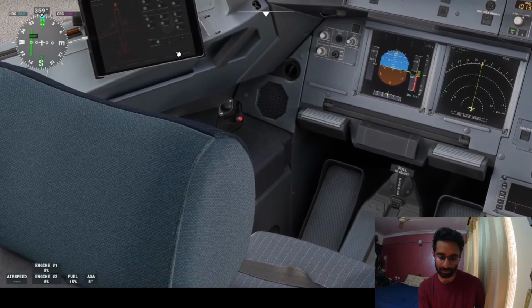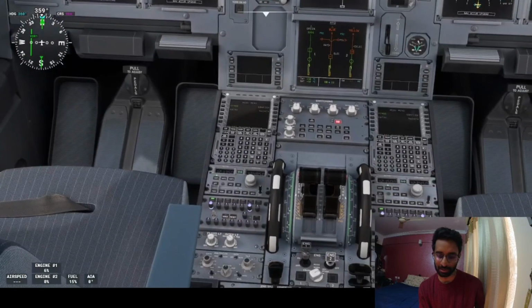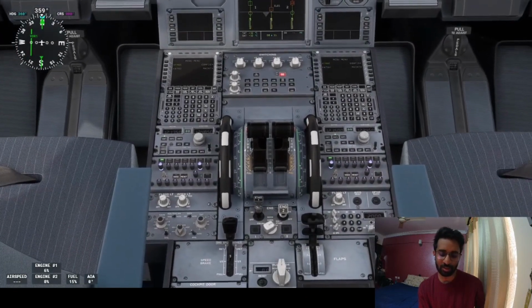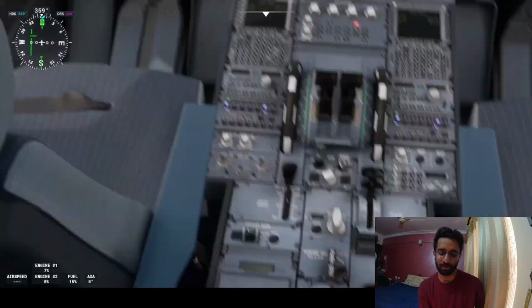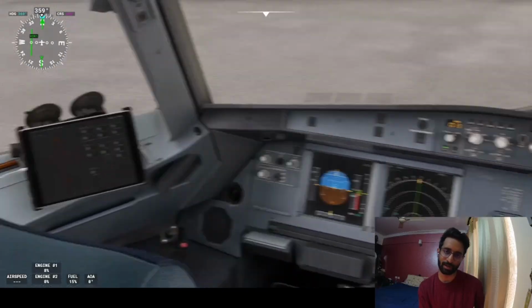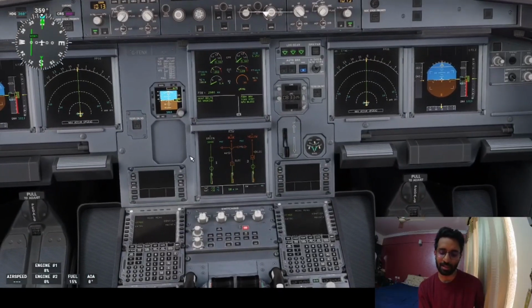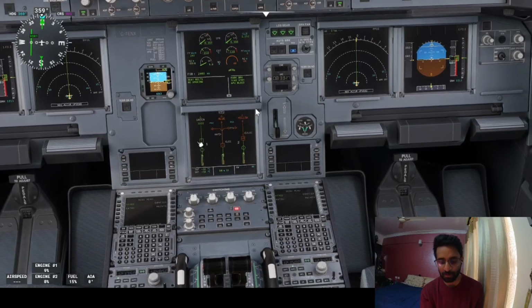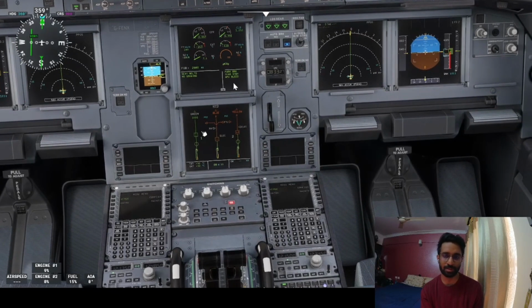So let's continue. Say I stopped the push. Assume pushback is complete. What do you do after pushback is completed? We set the parking brake. Once the parking brake is set, we ask him to disconnect and go. He can go. We can start the second engine without him being there. Again, this depends on airline SOPs. For us, once pushback is completed and the first engine is started, he can leave. So the nose wheel steering memo, if you check now, is not displayed anymore because he has disconnected it. Now we have controls back and he has gone.